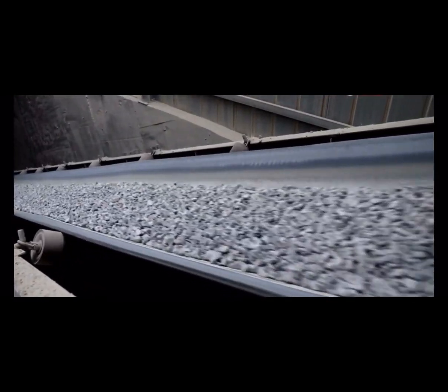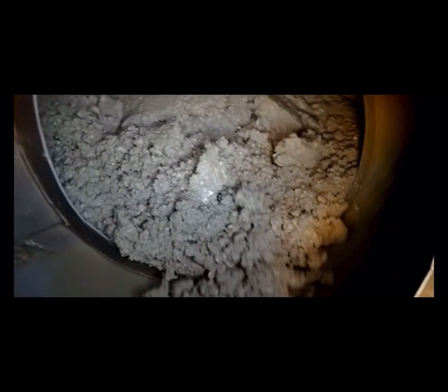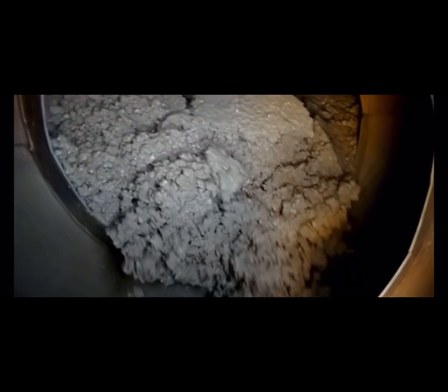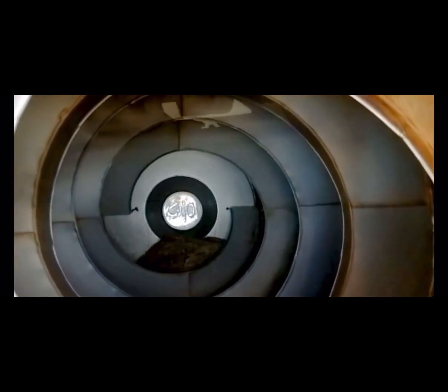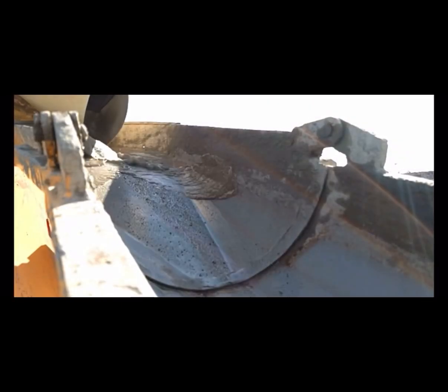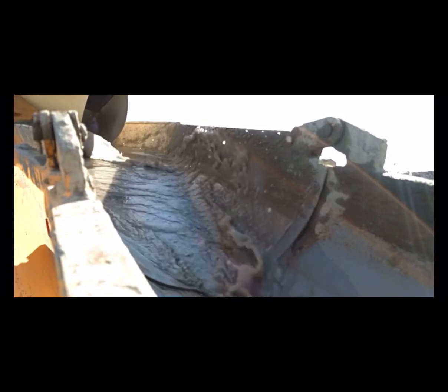When water and cement are mixed together, a paste called cement paste is formed. The hydration process generates heat and continues over an extended period, gradually increasing the strength and durability of the concrete. The mixing process continues until the concrete has a uniform consistency. During this step, it's important to check the workability of the concrete. The consistency of the concrete can be adjusted by adding more water or dry ingredients as necessary.